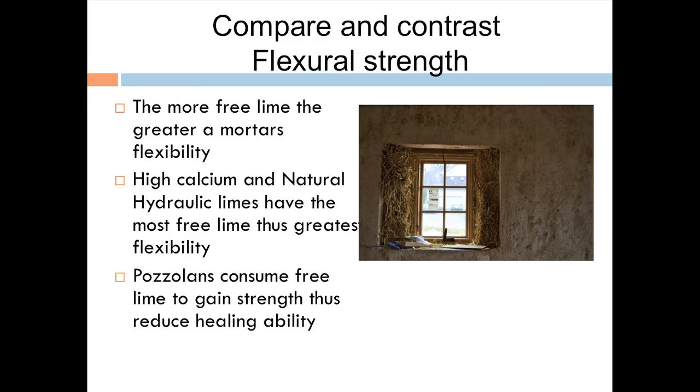Free lime is, when I talked about these plates in the lime that allow it to flex and move, if a fissure or a crack were to open up, this free lime, it's something that maybe has not fully reacted, and it's in the mix as it's setting, and it's still workable. What's evidence of that is in old castles, if you dig deep enough in these 10-foot thick walls, you actually find lime putty still in some areas that has yet to ever carbonate, because carbon dioxide could never get to the inner core of these walls, which are so dense.